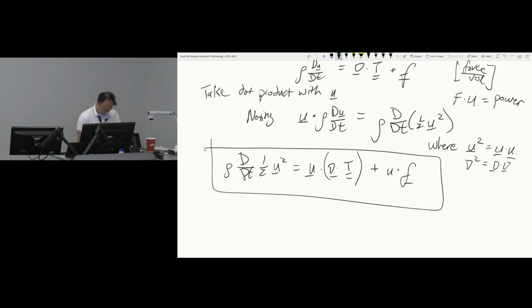Okay, so this is the mechanical energy equation. Let's interpret this together. The left-hand side is the time rate of change of the kinetic energy. Basically, if your control volume is just all those particles decreasing in speed, right? There's no elastic forces in fluid unless we're doing non-Newtonian stuff. This is work done by surface forces.